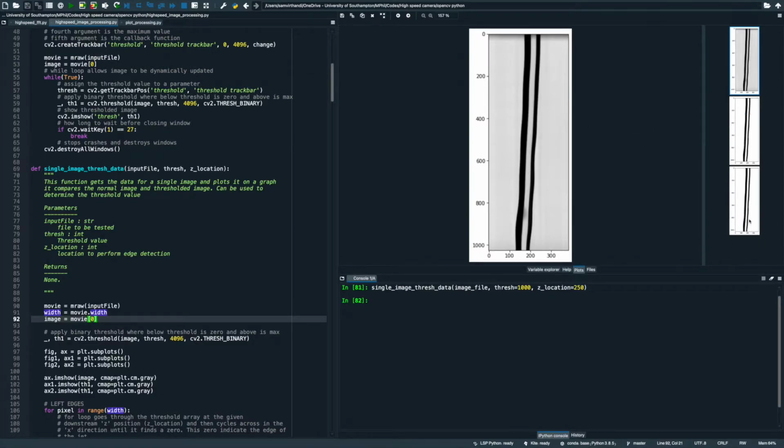So we've turned this grayscale image into a binary image, and you can see the effect that this has. If I show you the thresholded image, which is this function here, you can see that now the image is either black or it is white. There's no grayscale anymore. And this is very useful because then it allows me to detect the background, which I know is going to be 1, and the interior of the jet, which is 0. Now notice there is this white column in the middle here, and that's purely because water is transparent. So some of the light actually passes through it,